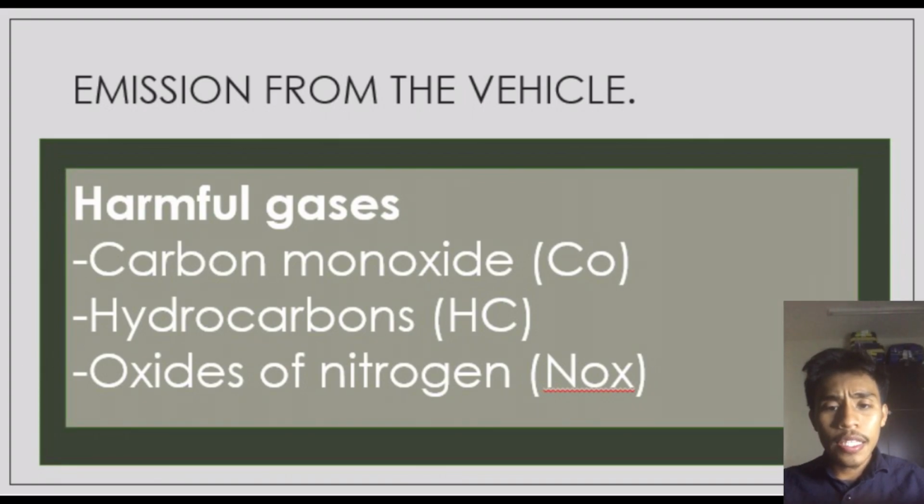Carbon monoxide is produced during incomplete combustion. Anything that leads to incomplete combustion increases carbon monoxide production. Other causes of high carbon monoxide production include a cool engine, misfiring, incorrect engine timing, defective and worn parts, exhaust system leaks, and a defective catalytic converter.